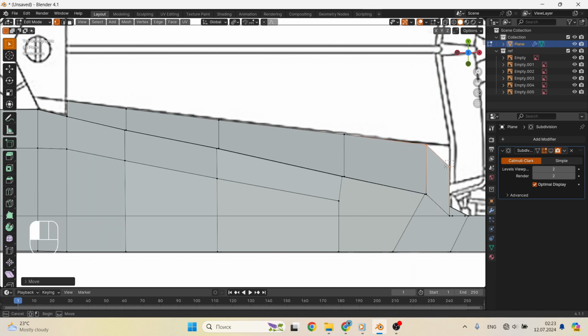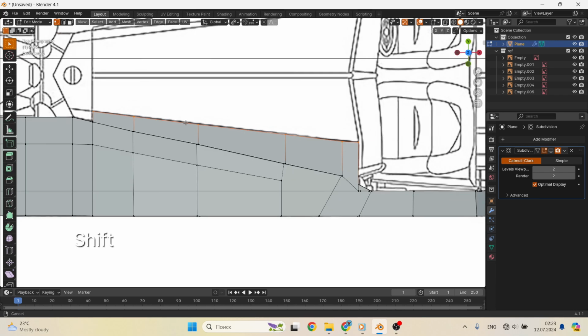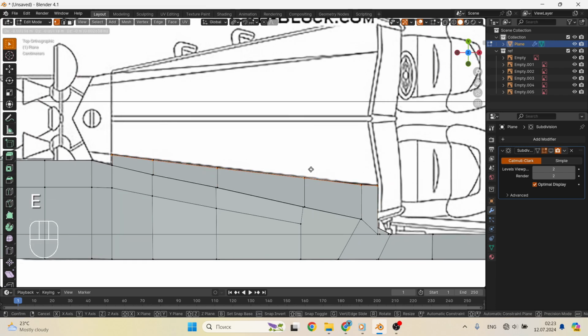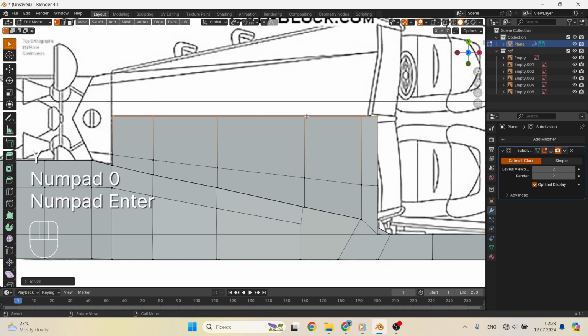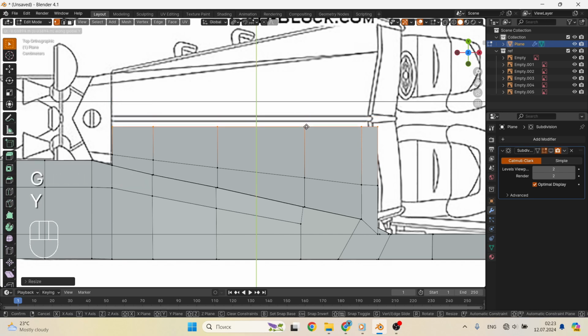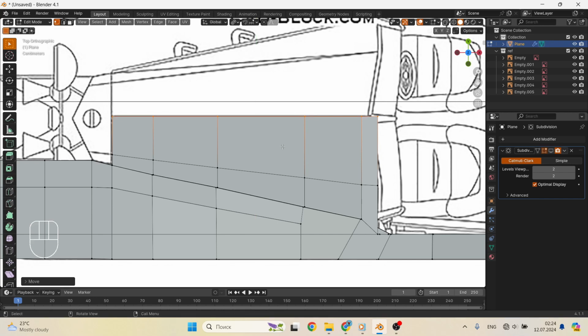6. Use creases on small or remote objects. Instead of adding additional edges to give rigidity to certain parts of the mesh, use the crease tool. This will keep the polygon count on your object low and simple. As the title says, use this technique on small objects or those that are far from the camera.